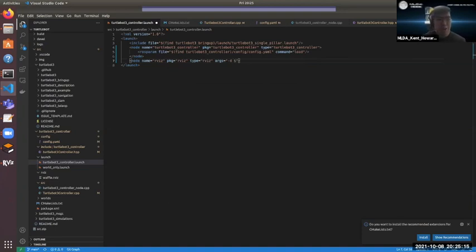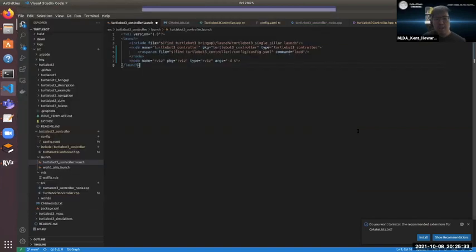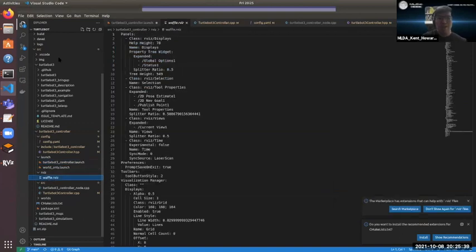So essentially, when you run RViz here, you can save the config and load it. So each time you run RViz, you don't need to put in everything, like add all the robot models and stuff. So how you do that is I've created my own RViz file here, which you will also have. So this is not coded at all. You use the GUI to create this.